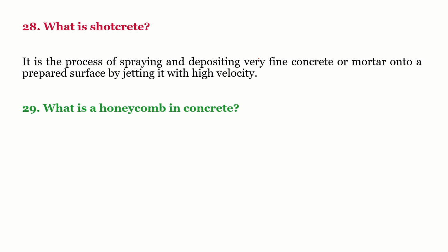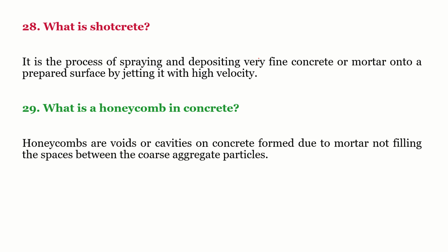And we have something called honeycombing. Even after concrete setting, once you remove the formwork, that is once you do the deshuttering, sometimes we find honeycombs. Honeycombs means you see some voids or cavities on the concrete surface which are basically formed due to improper filling of the concrete. When pouring the concrete, if you do not do proper compaction, you may end up with honeycombs.